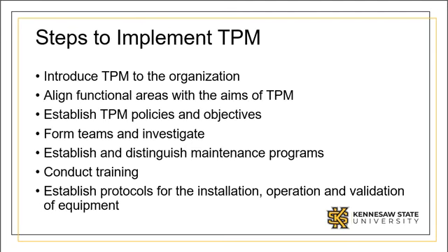If an organization sees TPM as a potential solution, it likely already knows of critical processes where TPM could help improve OEE and availability. Use dedicated teams of individuals to investigate the process and outline measures to move closer to an ideal state of TPM. As part of this investigation, items considered to be autonomous maintenance and scheduled maintenance should be categorized and grouped. Autonomous maintenance programs are deployed at the operator level, whereas scheduled maintenance programs are kept within the maintenance group's wheelhouse.